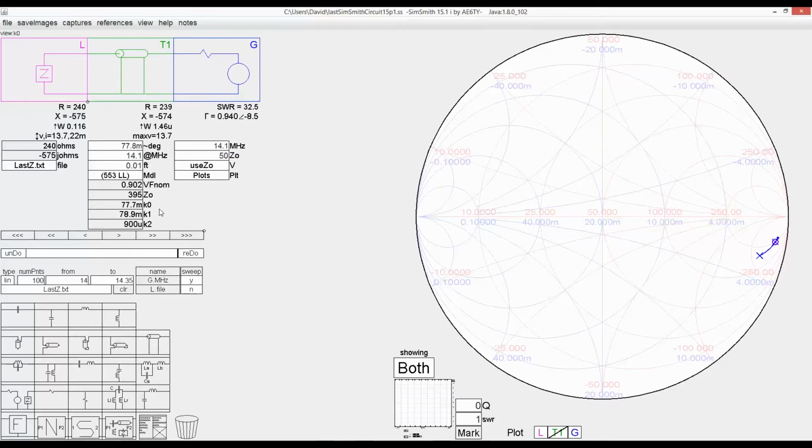So the polypropylene dielectric material, the webbing, well, I guess with ladder line, it's a section of polypropylene webbing, and then air, and then polypropylene webbing, and then air, and the net effect of the dielectric loss from that polypropylene is reflected in this set of coefficients, and I don't remember which one it is. I think it might be K2. Anyway, it's a pretty comprehensive model of the transmission line.